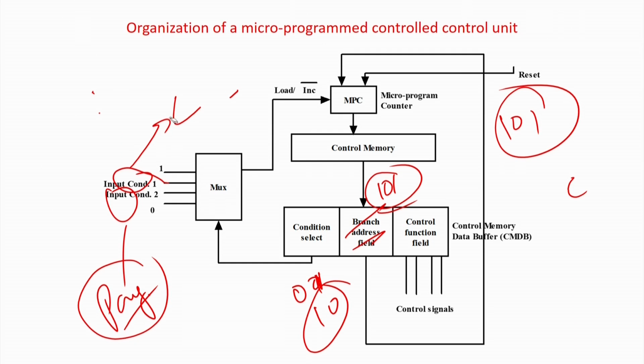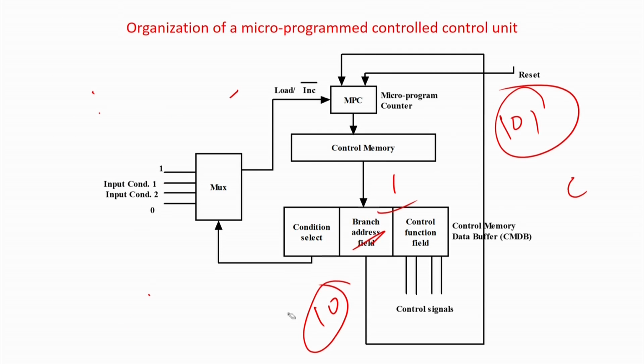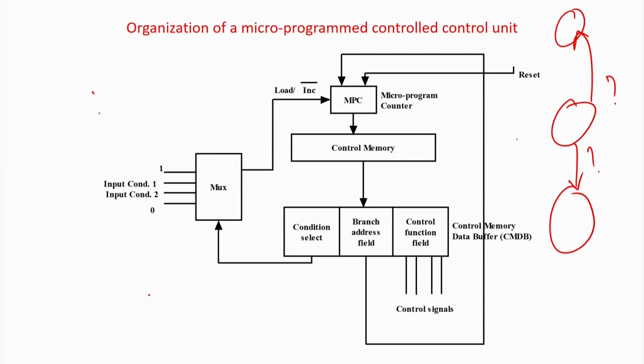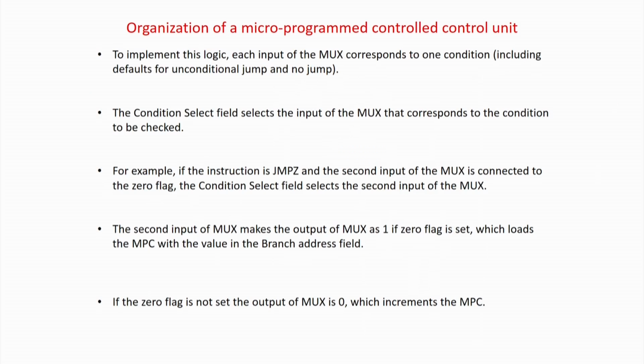So we have seen how this circuit implements the sequencing using a memory, because you have to remember that unlike an FSM, you do not have this flexibility where some condition checks are here and you go from this state to this state based on some condition, and control from going to here or going to here is done by state encoding. That is not possible. So we are implementing it in this nice, interesting digital design fashion. This is basically the organization of a microprogram control unit.